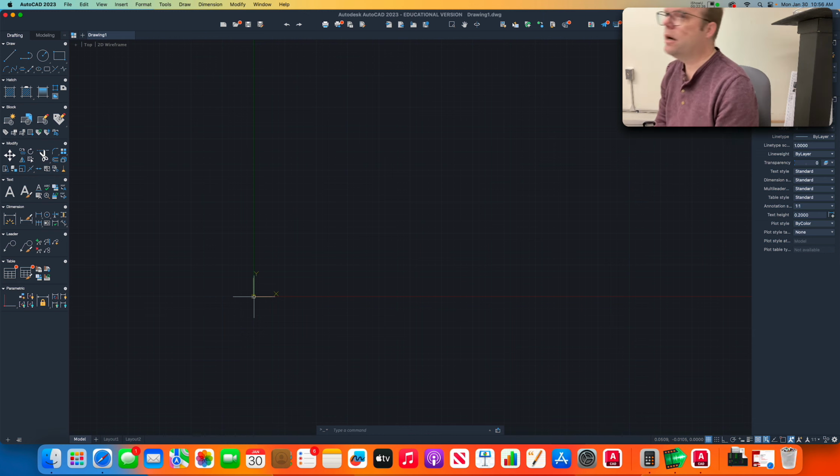Now, one of the things you will notice, if you move your mouse around, you see over in the lower right corner next to all of those drawing aids, that list of numbers that are changing. It's a list of 3 numbers separated by commas. The third one is 0 and it's not changing, but the first 2 are changing. That is X, Y, and Z for where your mouse is pointing right now in this grid system.